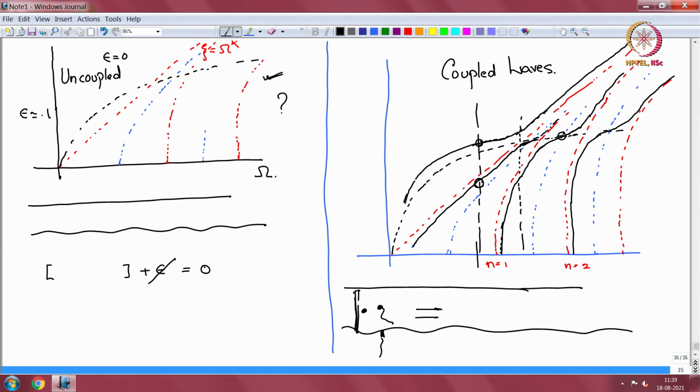Okay. So at this frequency, if I draw a vertical line, this is a possible wave, that is a possible wave. But now these are coupled, so whether you measure it in the sound field or you measure it on the plate, they will pick it up. Both of them are carrying the same wave, your sensors will pick it up.